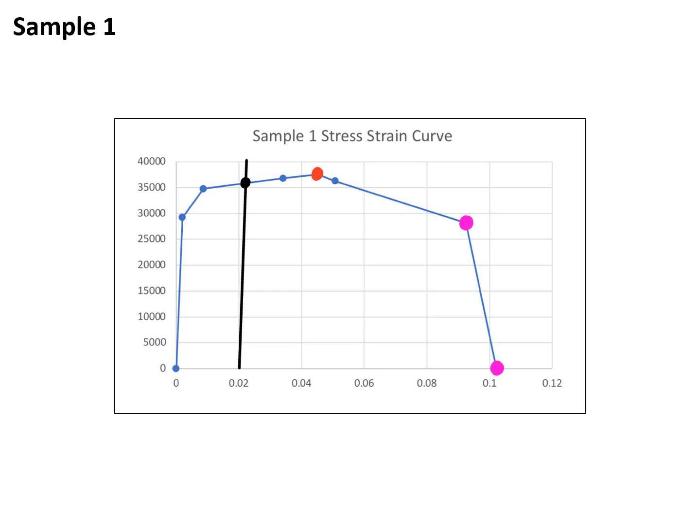retrieved from the test. The pink points on the curve represent the points where I had to use the change in distance given by the grips instead of the extensometer to finish the curve. The strain from those data points may be inaccurate as I had not measured the distance between the grips initially. So to estimate the initial length, I used the gauge length of my sample dimensions, where the smallest area would